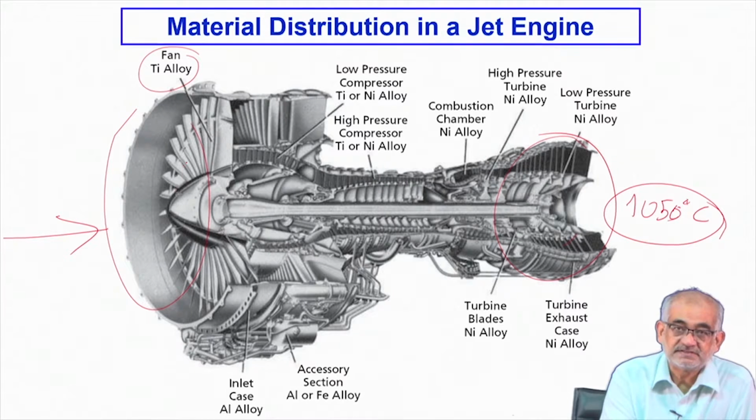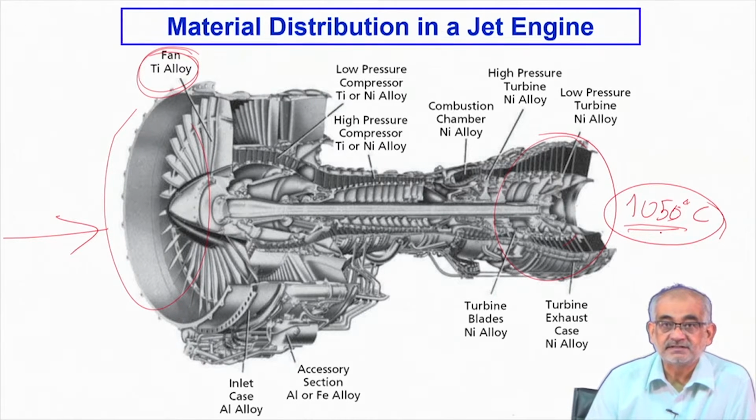So the turbine blades undergo very severe hits from the sand particles or whatever particles get sucked in. So these titanium alloys should have sufficient erosion resistance, right? Here, apart from erosion, because by now you don't expect so many particles to flow all the way there, but you certainly expect much higher temperature and high temperature attack. So you have to take care of the thermal fatigue, the creep damages, because you are subjecting it to elevated temperature at constant load, and most importantly oxidation at that temperature.